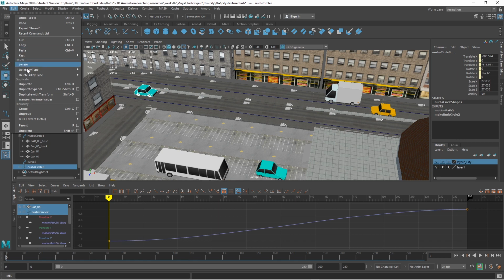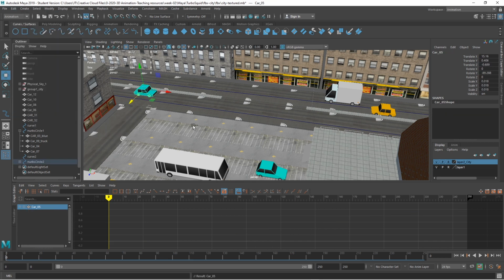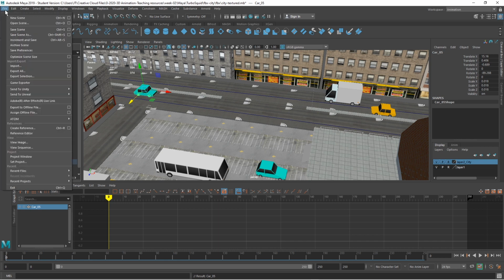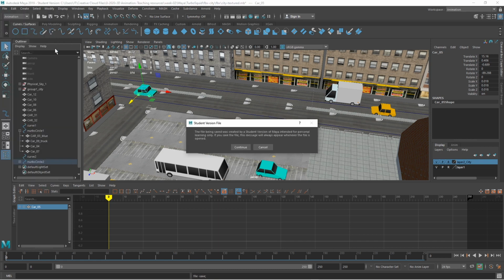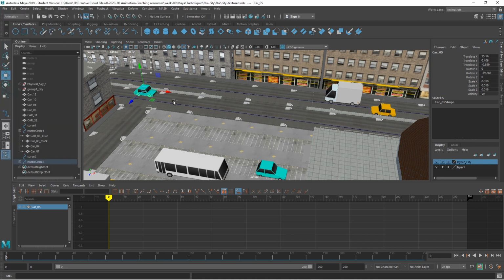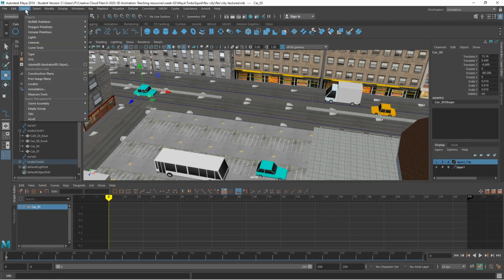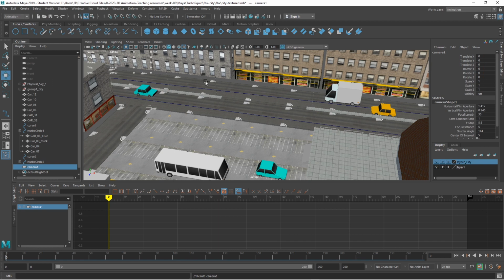And then I will move on to the next stage, which is setting up cameras so I can actually have a scene within this, and set up the kind of staging of the scene as I'm going forward. So to set up the staging within here, I can create some cameras. So cameras, you can go create camera, your camera and aim. Generally I use camera if I'm working in Unity, but camera and aim is a great thing as well.